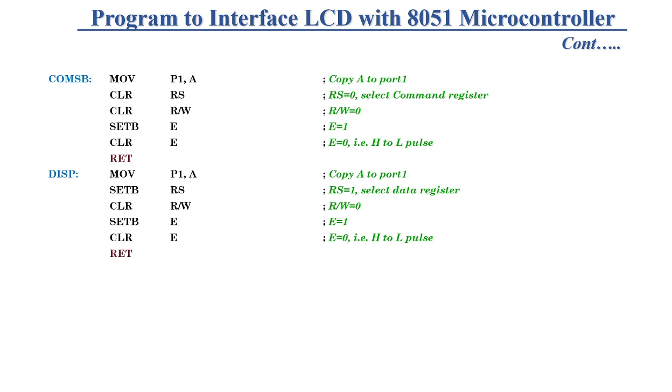And after execution of the instruction RET, it will return to the main program, where the next character will be displayed on the LCD. So in this way we can display any number or any characters or any graphics on the LCD. So here the delay subroutine is given.